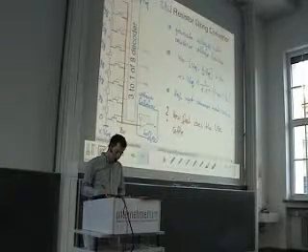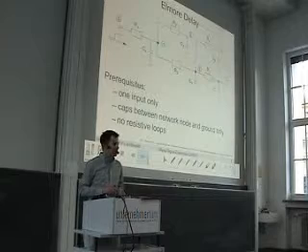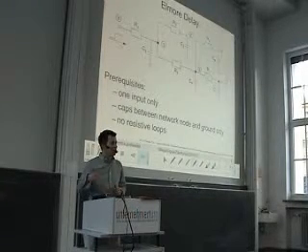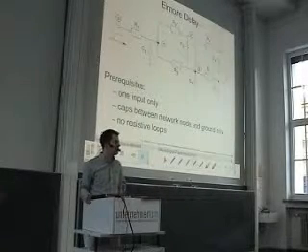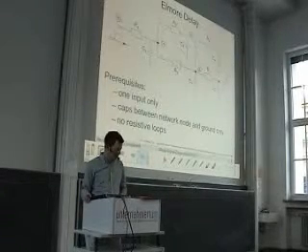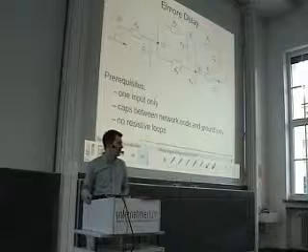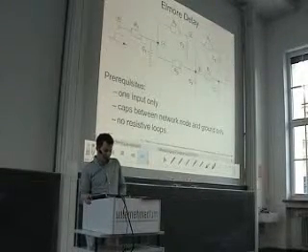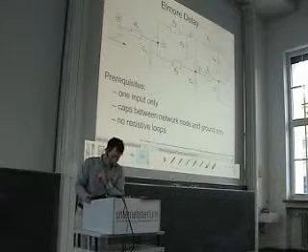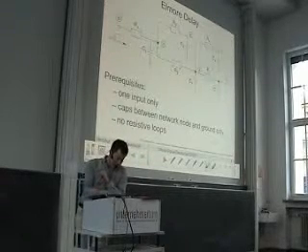One technique to do this is the so-called Elmore delay, and the people that have been in my digital lecture already know this formula. I have it in this course too, because it's also very useful to estimate the delay of these types of DACs. So the Elmore delay requires some prerequisites.